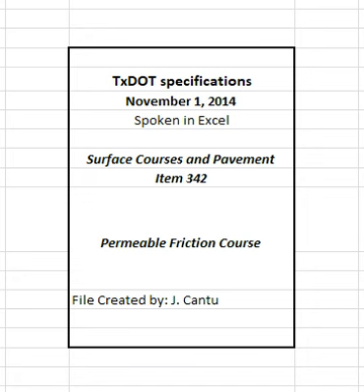Unless waived, the engineer will determine the Micro-Deval abrasion loss in accordance with Section 342.2.1.1.2, Micro-Deval abrasion. If the engineer's test results are pending after 2 working days, conditional approval of JMF1 will still be granted within 2 working days of receiving JMF1. When the engineer's test results become available, they will be used for specification compliance. The contractor is authorized to produce a trial batch after the engineer grants conditional approval of JMF1.